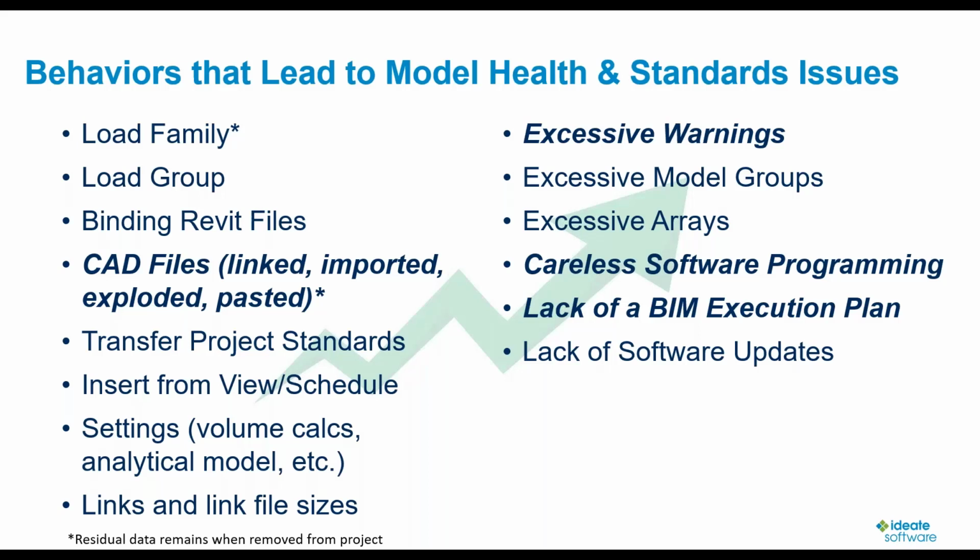And of course, importing and exploding CAD files is definitely the worst thing you can do, because once you do that, you get what we call Revit shrapnel. It was one of my students years ago who mentioned that when I talked about exploding CAD files, and I thought that was a good term for it. It brings in all that filth from the CAD files and embeds it in your Revit project. So if we have to use CAD files, link them, but try to avoid pasting and exploding them.